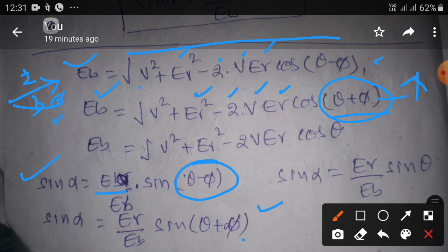So industrial people install capacitor banks in addition to synchronous motors. The synchronous motor runs at less than rated load but in the overexcited condition. Then the synchronous motor connected in the industry draws leading power factor.